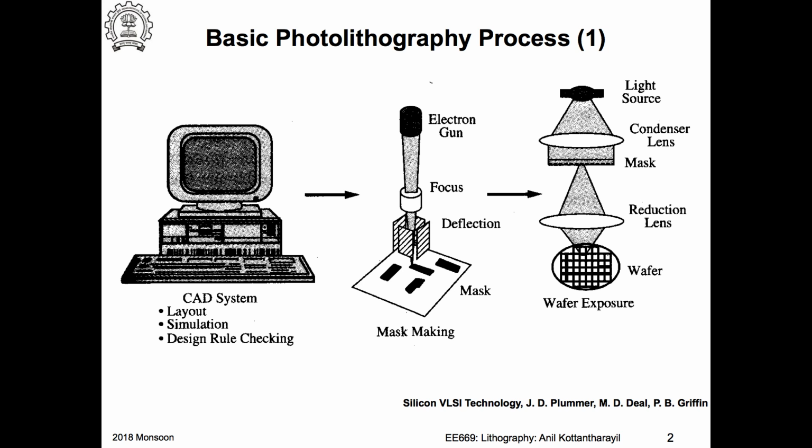Okay, so what he is saying is that this would take a lot of time. Because you have an electron beam, it has to be scanned line by line. So making a complex mask can take several hours on a single wafer, or maybe even days, depending on the system capabilities. But this one is very easy. It's just shining light once, right? So this goes in a few seconds.